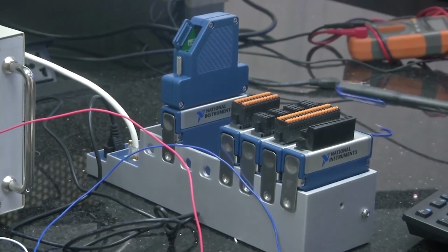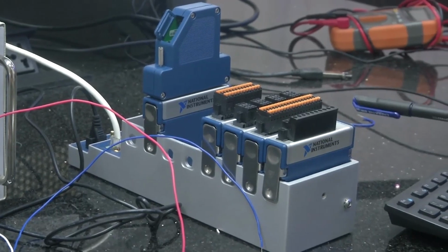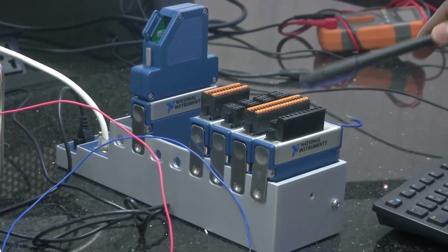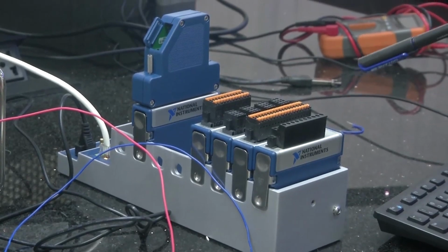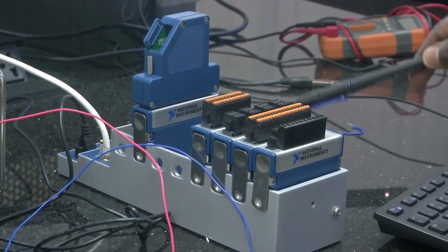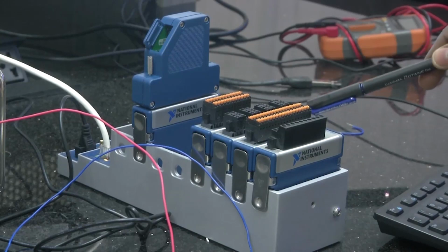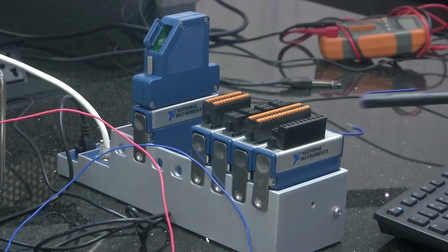One module is for generating analog voltage, and another is for acquiring analog input data, the signals, analog voltage as well as current. Anything can be acquired using this particular chassis. This is the NI 9207, whereas this one is the NI 9263. By using these two signal conditioning modules, whatever data is generated from the temperature sensor will be acquired,